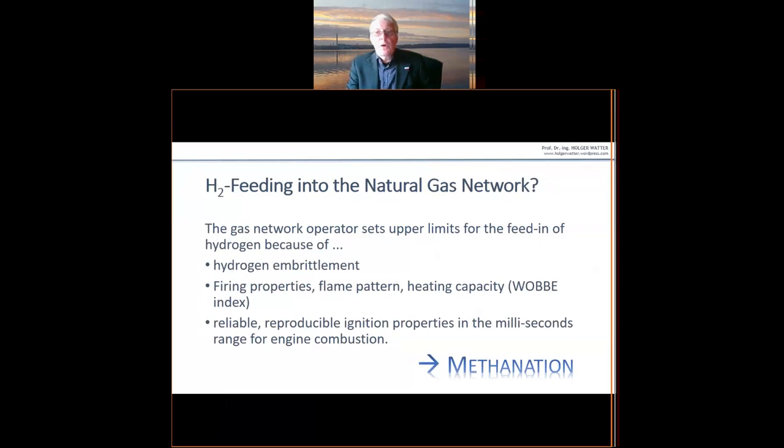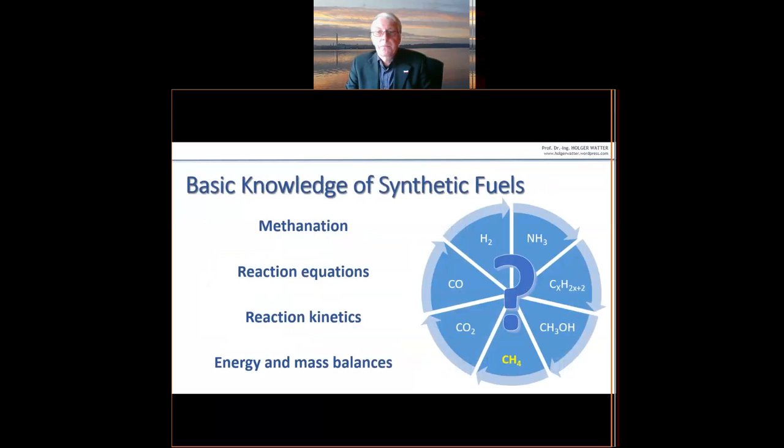The gas network operator sets upper limits for the feed-in of hydrogen because of hydrogen embrittlement, firing properties, flame pattern, heating capacity, named as Wobbe index, and reliable, reproducible ignition properties in the millisecond range for engine combustion. One possible solution to this problem is the methanization of hydrogen. Let us consider the details, such as the reaction equation, as well as energy and mass balance.